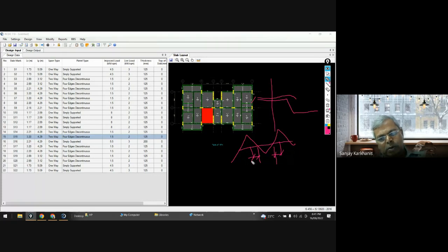And this is my support. So theoretically, I don't need any reinforcement over here. So 50%, even then I'm providing 50% over here at bottom. And the remaining 50% I am providing over here to take care of this moment. Got it? So that is that portion, L by 4, L by 6. You can find it out with the help of the normal bending moment diagram.